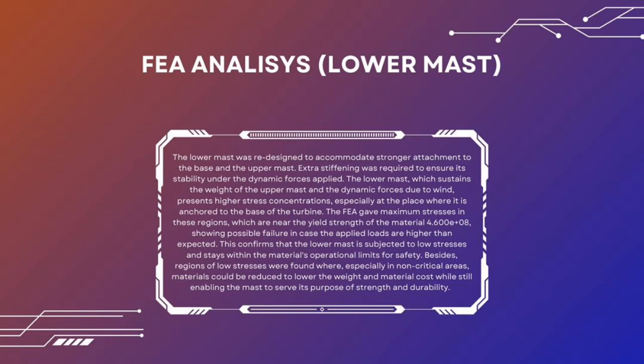This confirms that the lower mass is subjected to low stresses and stays within the material's operational limits for safety. Besides, regions of low stress were found, especially in non-critical areas, where material could be reduced to lower the weight and material cost while still enabling the mass to serve its purpose of strength and durability.